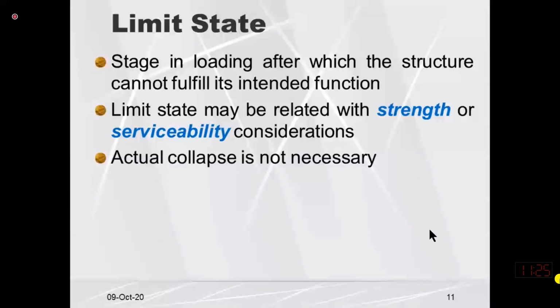So limit state may be related to strength or to serviceability considerations. Serviceability means deformation or strain limit. If we put the limit on the stress, it is called strength limit state design. If we put the limit on deformation, it is called the serviceability limit state.